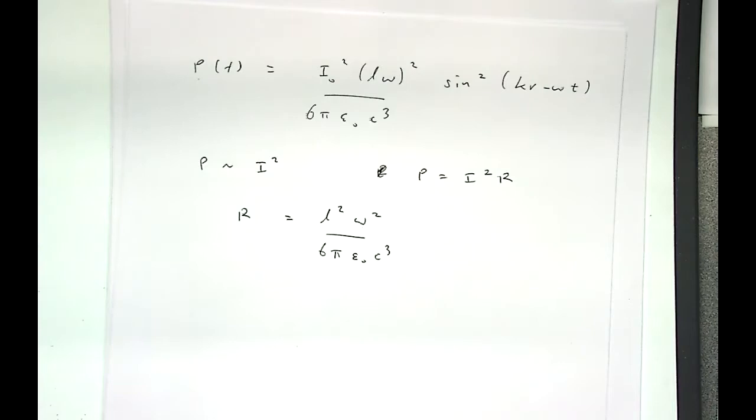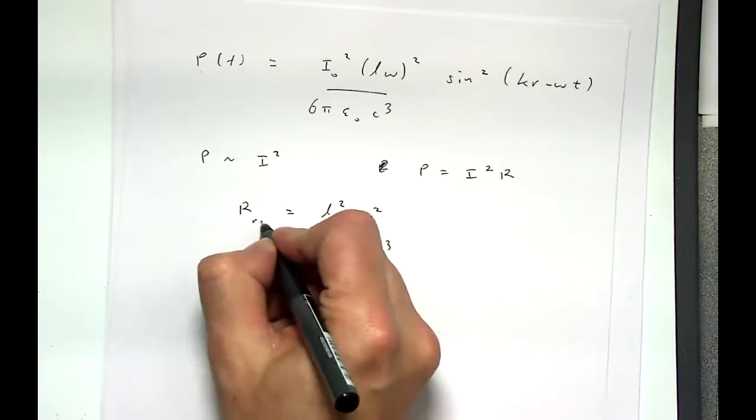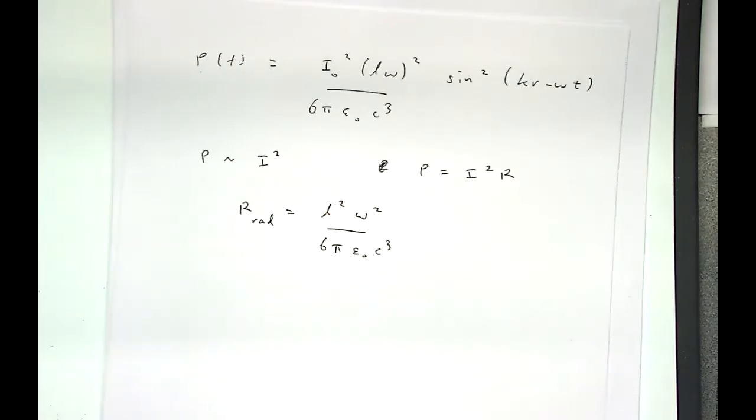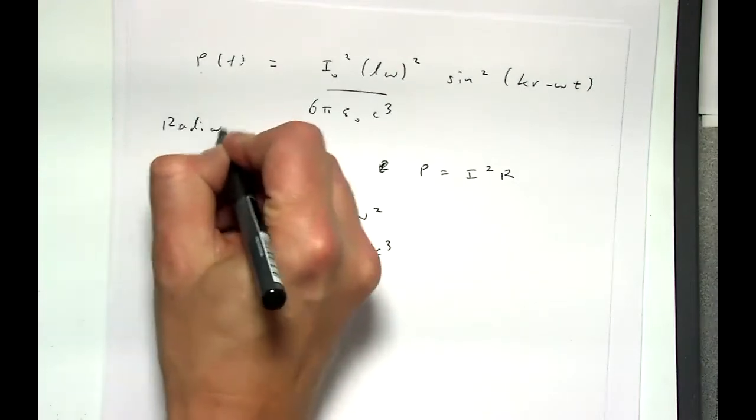So you can see that as the distance over which the current moves grows, the radiation resistance, as we're going to call it, increases and less power is emitted. The same thing is true as the frequency rises. Sorry, as the radiation resistance goes up, the power goes up. Sorry, not down, goes up. So the radiation resistance tells me that as I move the current over a long distance or its frequency rises, the radiation resistance goes up and the amount of power for a given current also goes up. So this is what we call the radiation resistance.